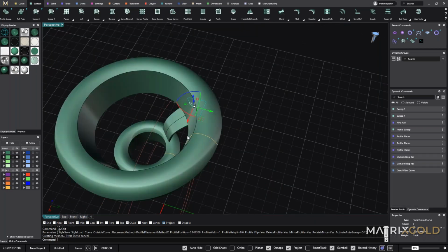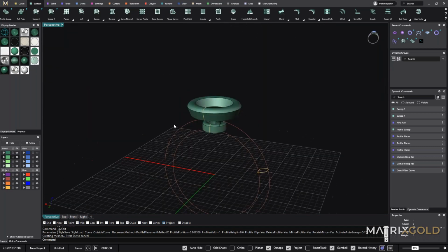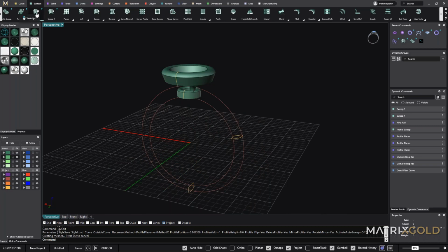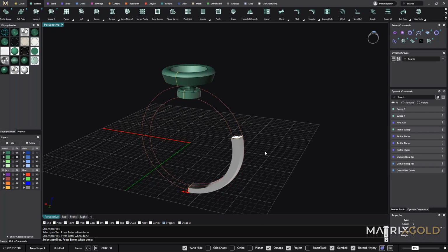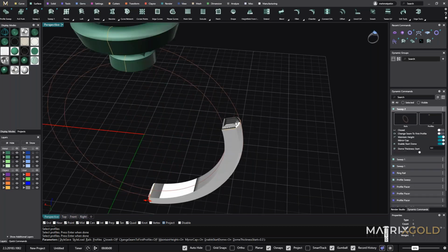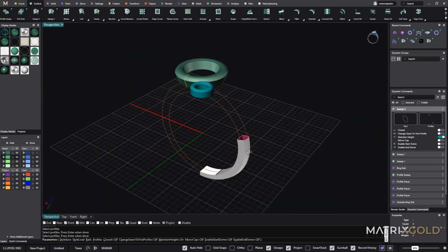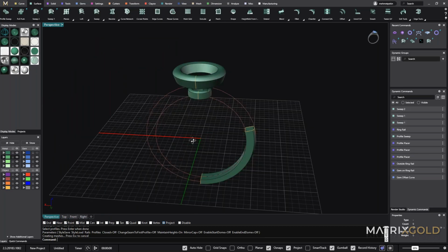And it's very easy. And I want to make this side, so I go to the sweep two option and select these two parts and select these two of them. And I don't want to make some dome parts to here, so select mirror cap and select enable start dome and enable, and just close these buttons here. That's okay, I think. And I click it.